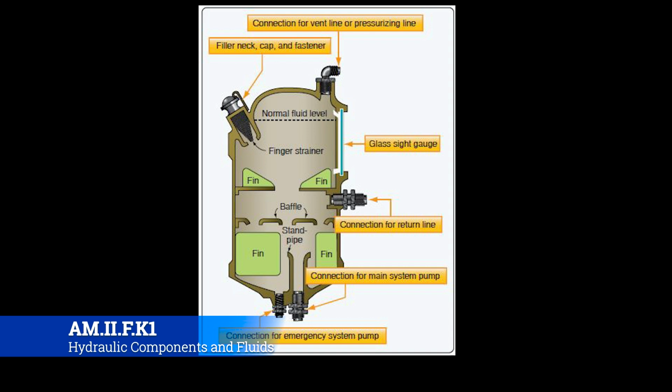Now, what ends up happening, as we'll see in a minute, is that hydraulic fluid is going to cycle through the system. There's a bunch of reasons for that. It could be cooling, cleanliness, you name it. But either way, there's going to be more hydraulic fluid than there is room in the actual lines, and that's what the reservoir does. Now, a non-pressurized reservoir is usually vented, so that the hydraulic fluid can be pumped up into the reservoir and then sucked back down into a pressurized system.